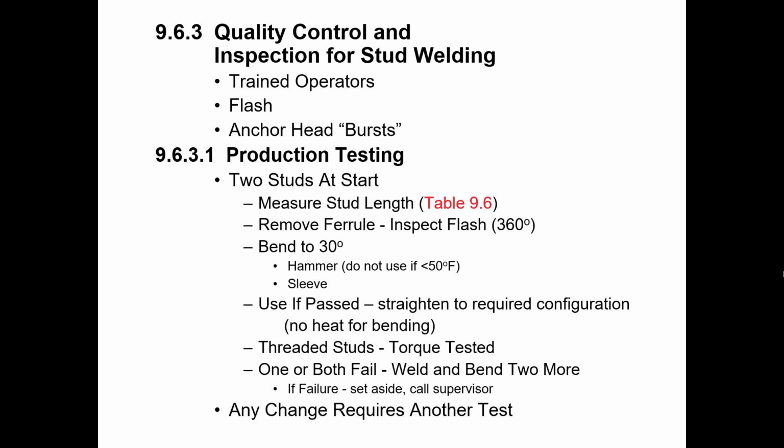Threaded studs are a little different for hopefully what are obvious reasons. You don't want to damage the threads, so you're going to do a torque test instead of a bend test, where bending that over would damage the threads.